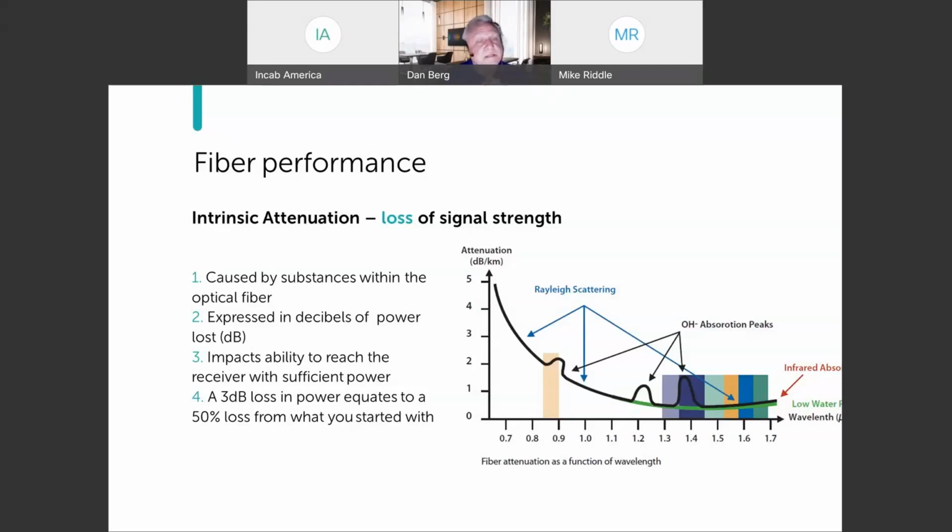A beam of light passing through this structure will have some of its energy scattered by these objects, and this is called Rayleigh scattering. If the scattered light maintains an angle that supports forward travel in the core, then no attenuation occurs. Some portion of the light will travel back towards the source. This is called backscatter. And this is what an OTDR uses to test the optical fiber.